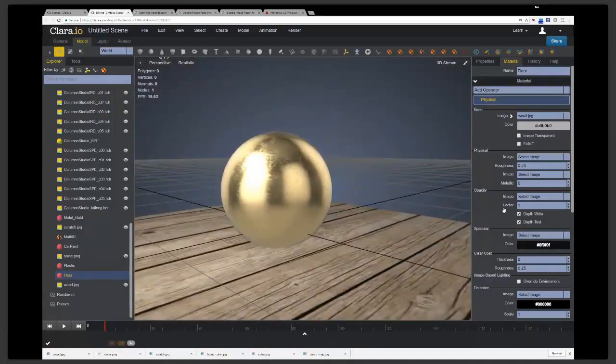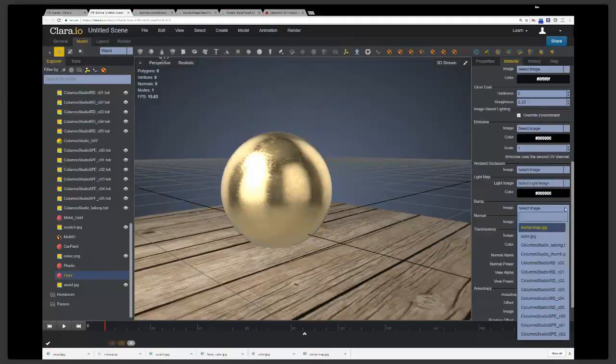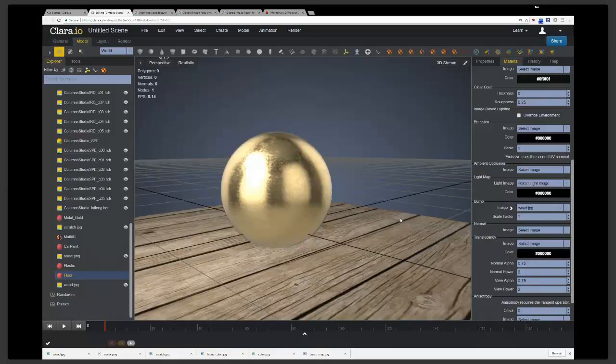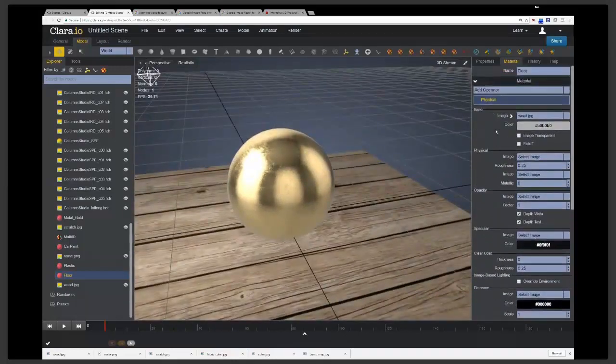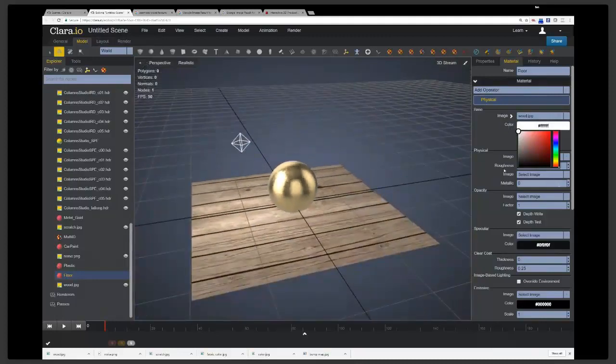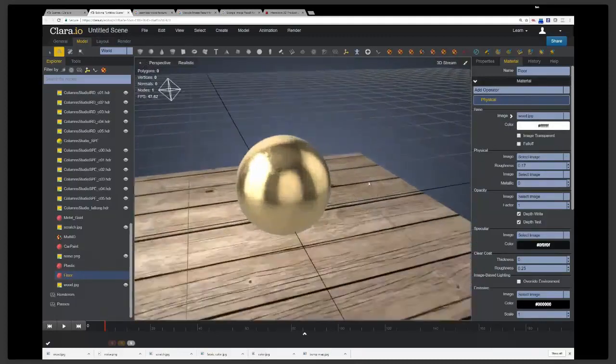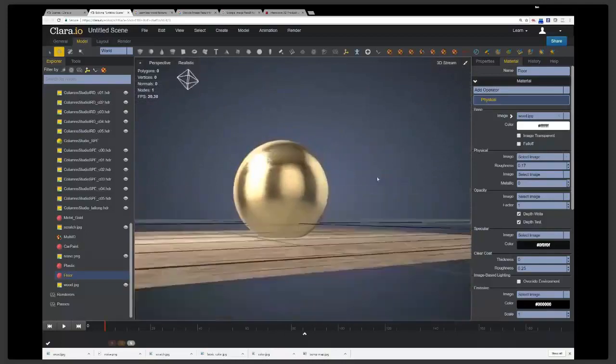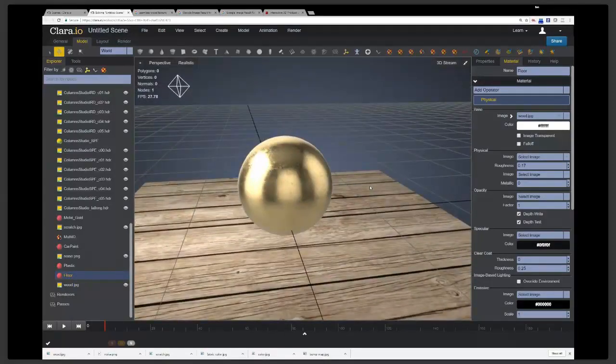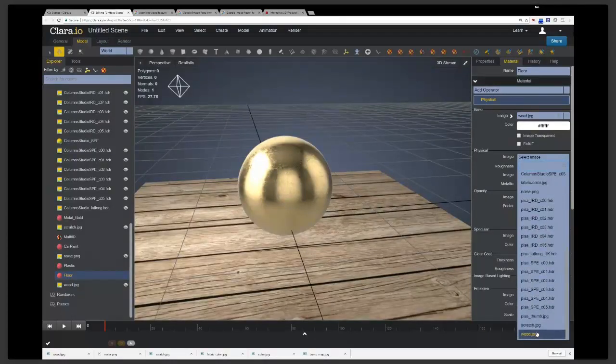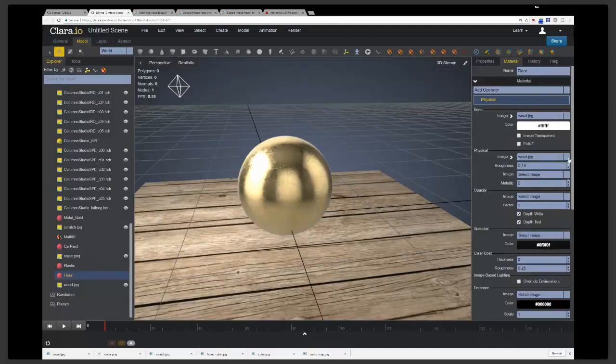Again, it looks very flat. So the first thing I would recommend is adding a bump, using the same image in this case as the bump map. It's very diffuse, so I can make it a little bit rough, but I don't think it's going to matter that much. I guess next, that's not horrible. But I guess next, you can actually vary the roughness based on the wood map as well, or you can find something else that sort of maps it very closely. But that can actually add a lot of sort of detail to it. Let's see if that can work.